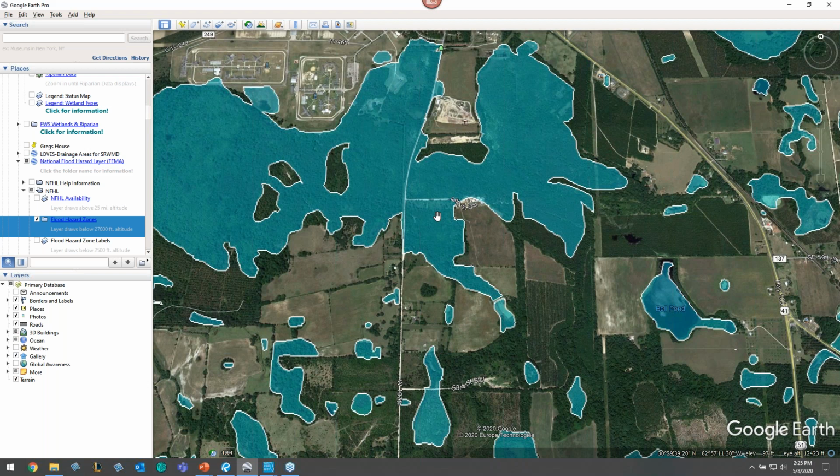The way I like to explain it to people who've never heard of this process is, imagine you have a cup full of water. You put ice in that water, what happens? It overflows. Well, the same thing happens here. You're adding more dirt to the floodplain, or it's possible you're adding dirt, you don't know that for sure. You have to know the elevation of your floodplain to see if your job is actually adding dirt.